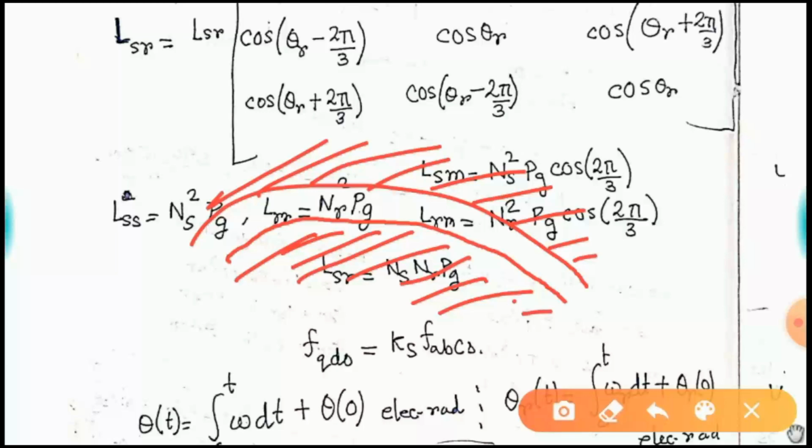So irrespective of the geometry of the air gap, your permeance depends on your material and the distance between them, right? So here that perpendicular distance always remains constant. In this total thing we can expect a constant permeance along this path.